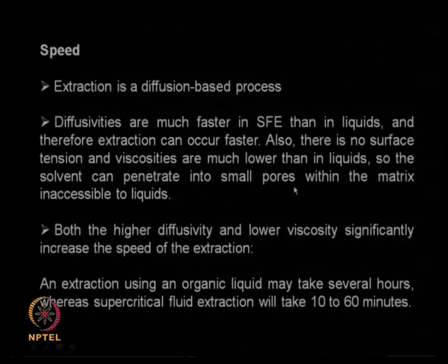So it can enter very small pores and matrices which are inaccessible to liquids, and the speed of extraction is very fast. If an organic liquid takes several hours to complete the extraction, with a supercritical fluid I can do it in 10 to 60 minutes. So we are talking about an improvement in speed by a factor of 3 or 4.